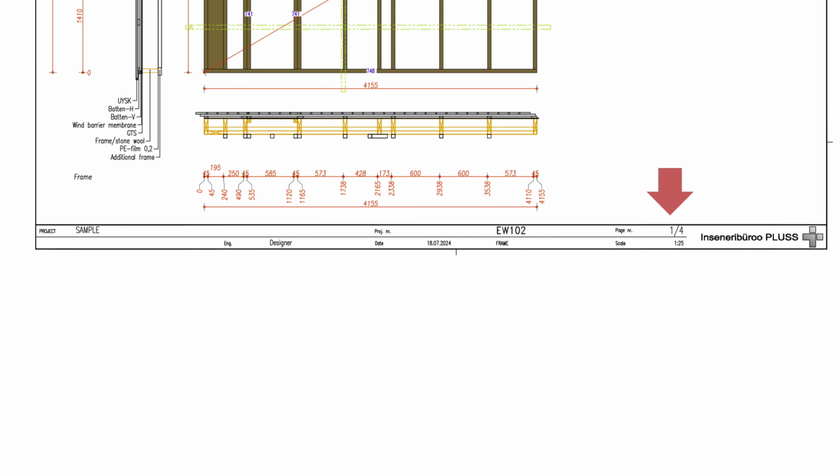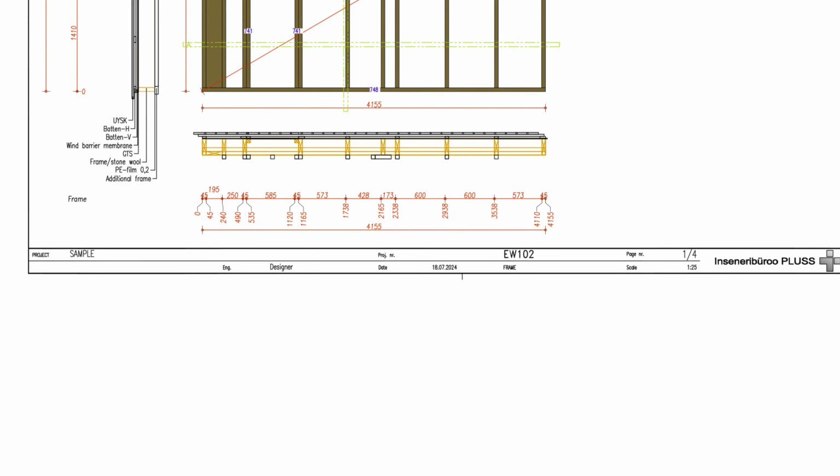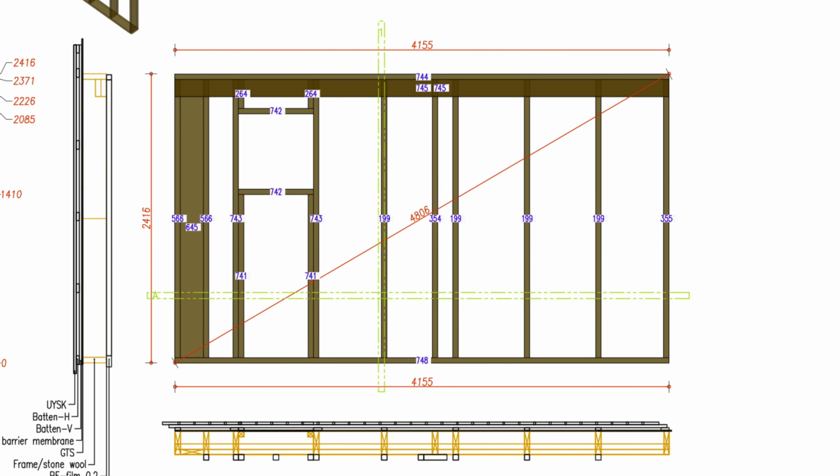The left number indicates the number of the drawing in the whole set of technical drawings, and the right number indicates how many drawings are in the whole set. Some other details are also included in the title block, like scale, date, and special amendments. Each detail in the element is assigned a position number for identification.